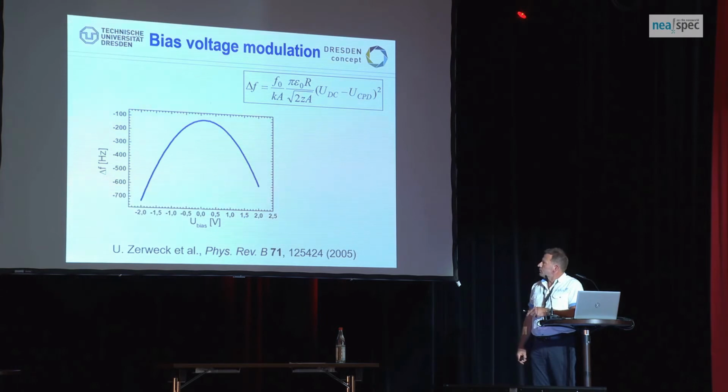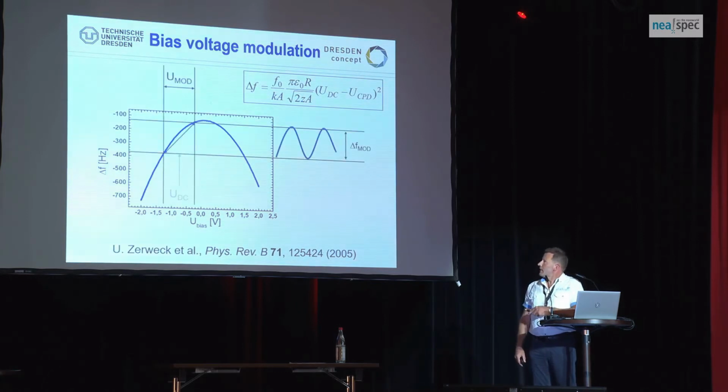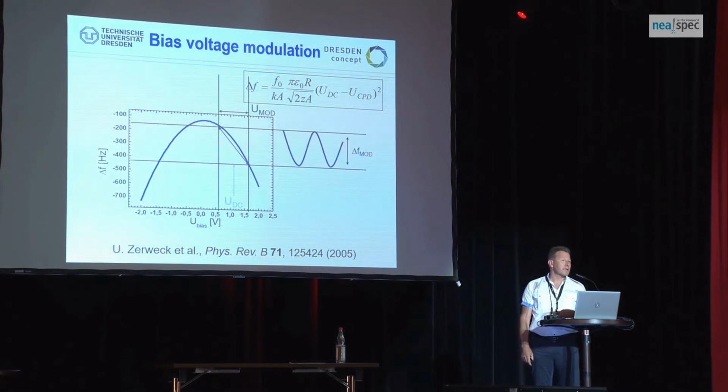Please note that this point, the 0 bias, which is the external DC, is not aligned to this apex simply because we still have the work function difference, right? So we want to measure that now, and what we do is simply apply a DC voltage and then basically make a modulation. On the left side, you see nicely this is a slope being positive. You go to the right side, you will have a slope that is negative.